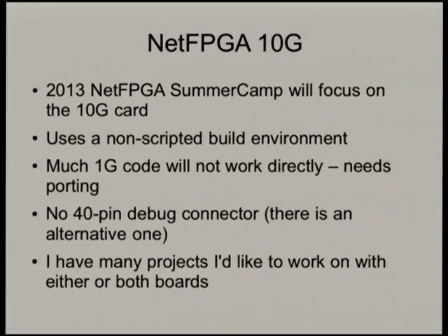This has been a major stumbling block for the NetFPGA project, and they've had to rely much more on the proprietary GUI based development environment, and they're trying to move a lot of the code that was written for the 1G card across to this new environment for the 10G card. It's not really that new these days, it's a few years old, but it's hard for them to transfer it all across. The other thing is that the 10G card doesn't have the 40-pin debug connector on it, so it can't easily be used in the same way as a development platform.